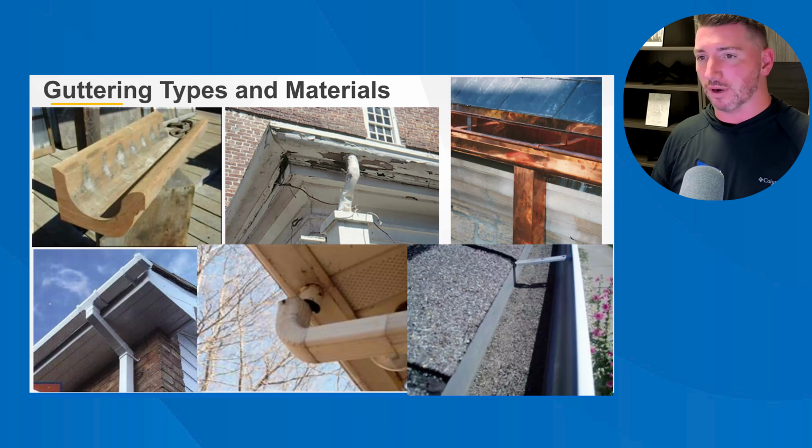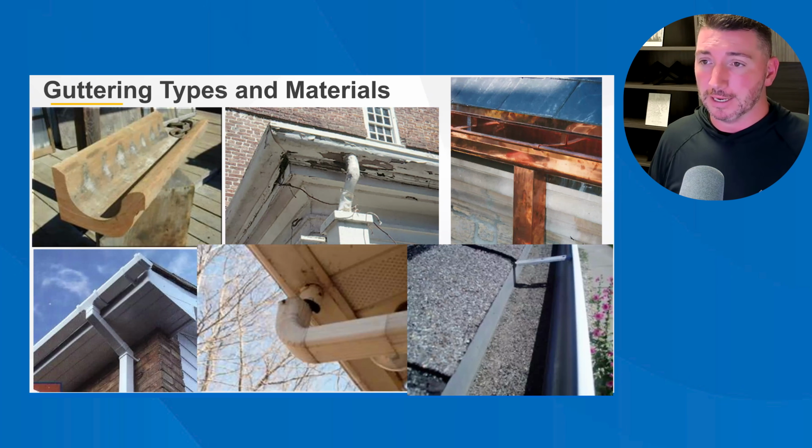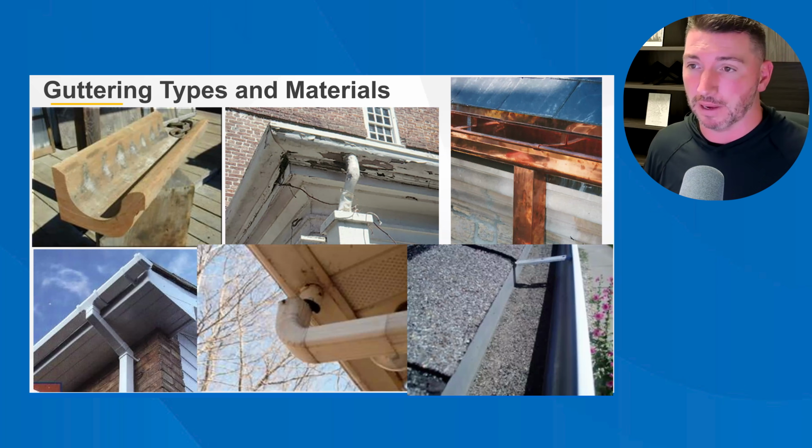The big difference is whether or not they're using 5 or 6-inch gutter and whether or not they're using 2x3 or 3x4 downspouts. The vast preference that I've seen is to upgrade to a 3x4 downspout, even if you only have a 5-inch gutter, just because you want the capacity of what can flow out to be better. And there's really not a tremendous drawback to having an oversized downspout.